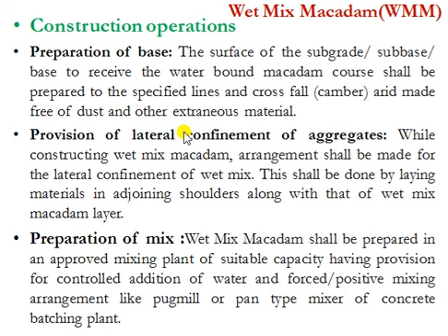So subgrade, subbase or the base: this is the layer which receives the wet mix macadam pavement. So the layer which is beneath the wet mix macadam pavement should be prepared first. If there are any grasses or any waste materials on the base, subbase or subgrade, those should be removed first.